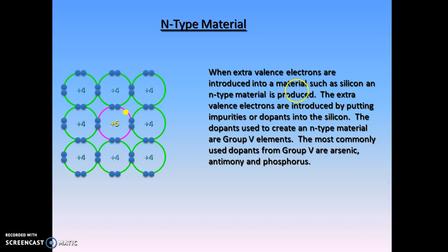Okay, now N type material. In the N-type semiconductor, electrons are the majority carrier. N-type semiconductors are created by doping an intrinsic semiconductor with donor impurities. Here silicon is used. Silicon has 4 electrons in the outer shell. Now, if a pentavalent impurity like phosphorus, arsenic, antimony is added, then this impurity has 5 electrons in the outer shell.